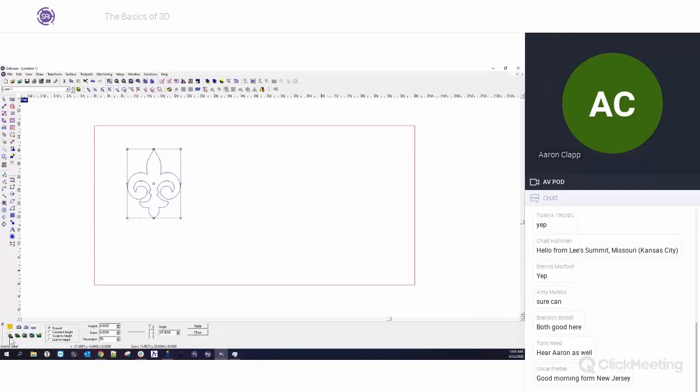The way that we do that is we select Add down here, and we're going to go through all these, and I'm going to try and go as quick as possible. The good thing is you can get the recording and watch it later if you have more questions or want to see it again. So first of all, we're going to add to relief. I'm going to select flat. I'm going to select normal, and I'm going to say height and base 0. I'm also going to set my resolution at 50.